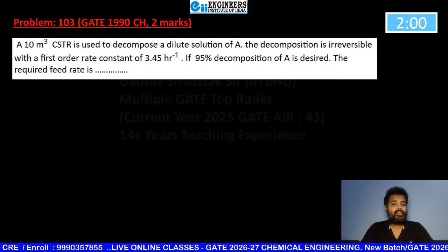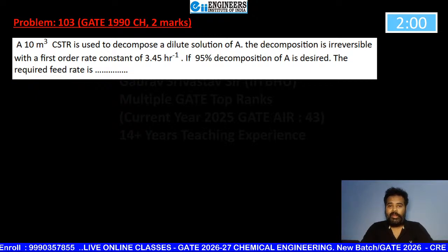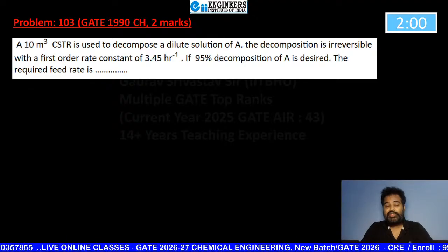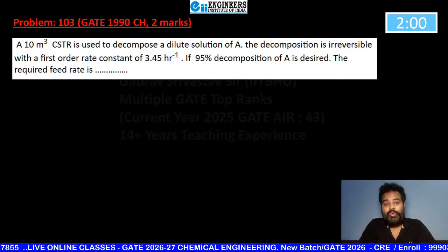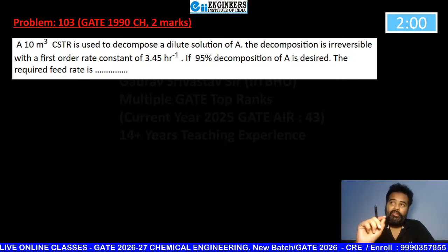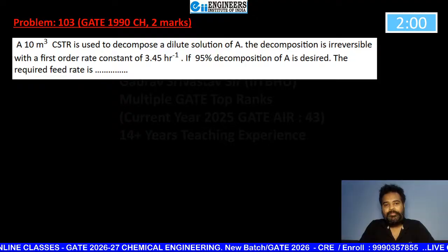So beta, in the previous question, again I want to discuss, that was an exception case. That is an exception case, which is why it is asked, for a zero order reaction, because the rate is independent of C_A, and clearly for that case, for finite V you will be able to achieve that value with the help of the design equation.